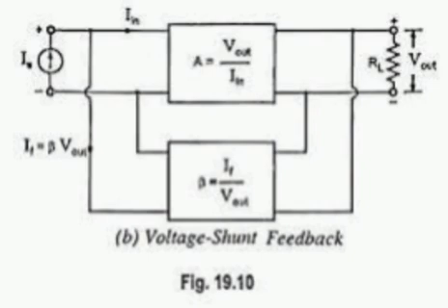The voltage amplifier output is given in shunt to beta, input is given in series, VF, beta is dimensionless. Voltage series feedback stabilizes the voltage gain. Example: common collector, non-inverting amplifier. Current series topology.